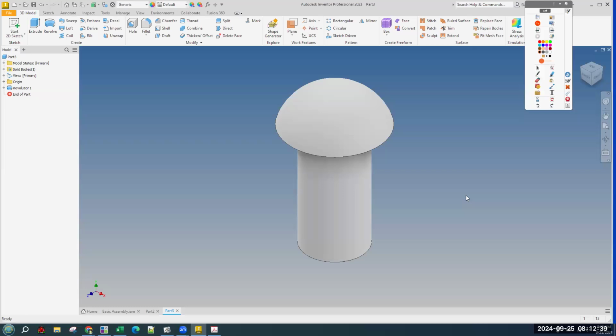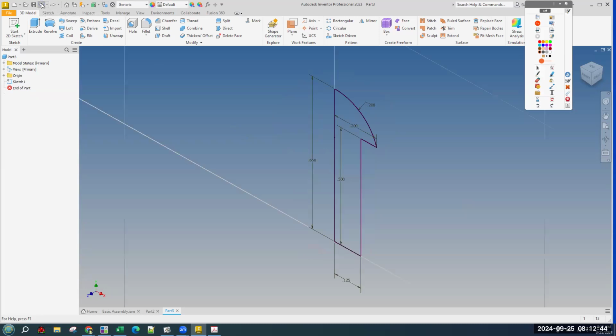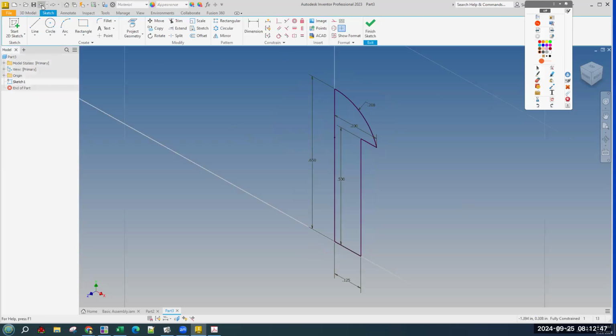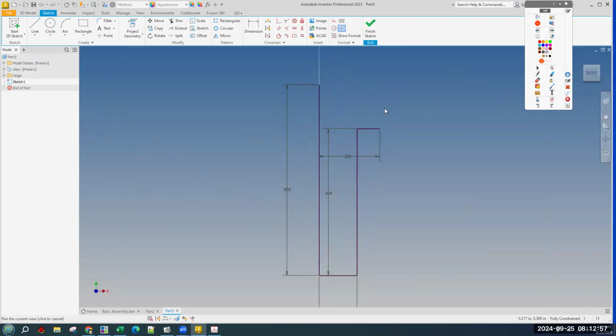What's that? The arc? You said, can you get help on the arc? Okay. So you are up to this point. You have all the other parts except the arc. At this point, which I think you may be past, use the 3-point arc tool, which is the default. First click on the top endpoint here, second click on the other endpoint here, make it look slightly arced in this direction, and then dimension the actual arc to 0.208.